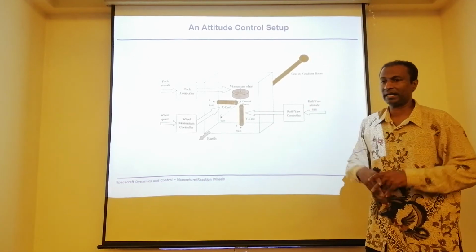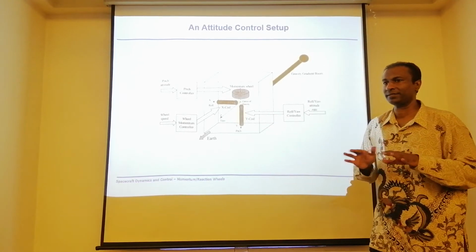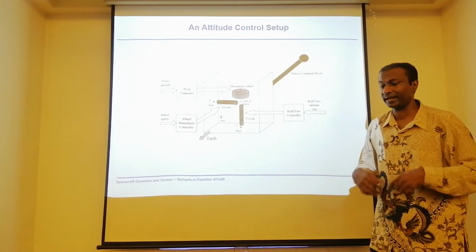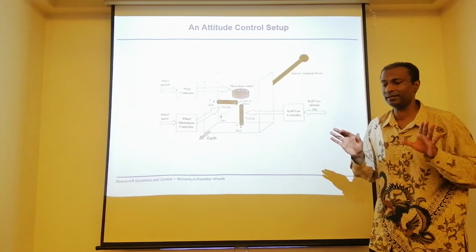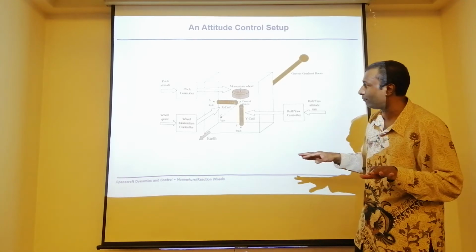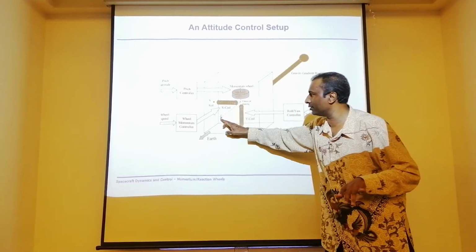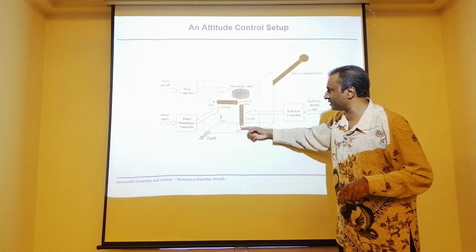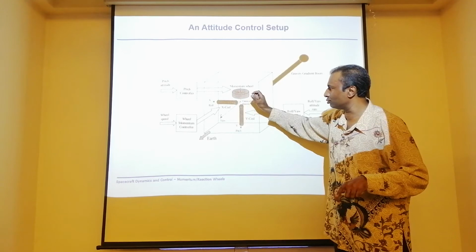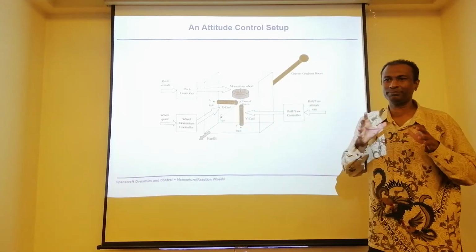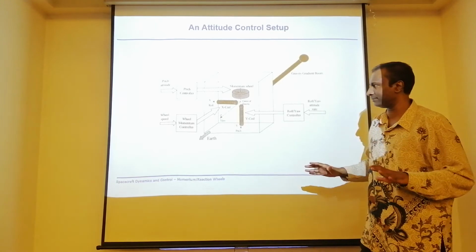Momentum wheel. I have a momentum wheel, that means what? My pitch axis is done. On the pitch axis, I have active control already. Then I can provide passive control, or rather gyroscopic stiffness, for roll and yaw. The pitch axis can produce roll and yaw passive stiffness. Okay, done.